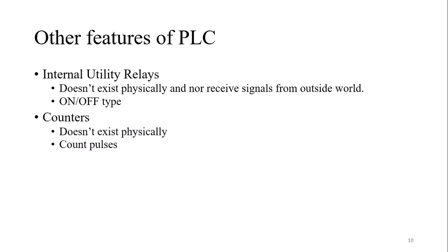Then there are counters. Counters means to count pulses, correct? Like your energy meter, the meter that is installed outside your home, to count how much electricity you consume. There's always a blink. That's a pulse, correct? That's a counter. It counts how many times you performed this function. Here, it does not exist physically. We have not seen counters in our energy meter, but yes, it exists, and it counts pulses. So the PLC has other features to count things.